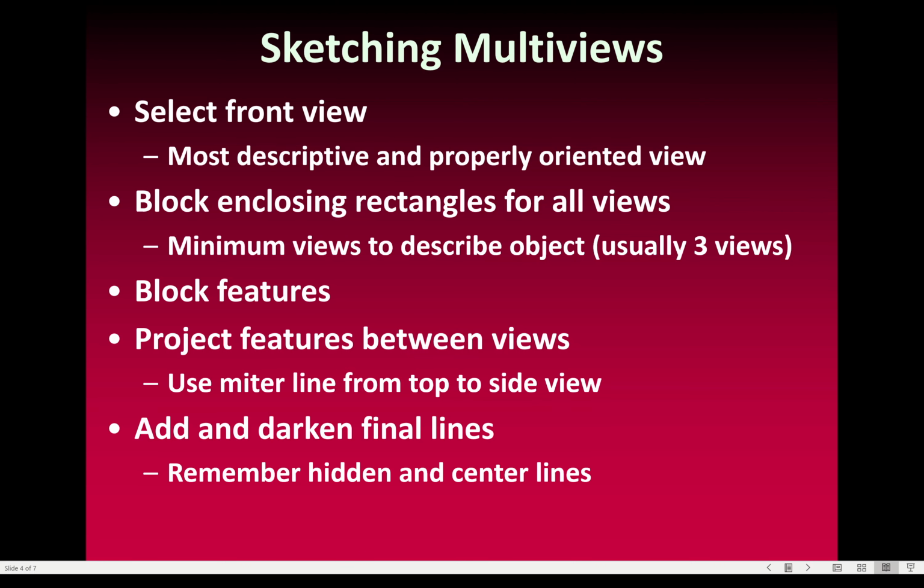Once you get it laid out, you can darken anything out, make sure you include any hidden lines, include your center lines, and that pretty much ends the drawing until we get to dimensioning. If you do have any construction lines, those you'll want to erase. You may have used them to just make sure everything's lined up, but ultimately want to erase them. So that lays out how to create that multi-view sketch.